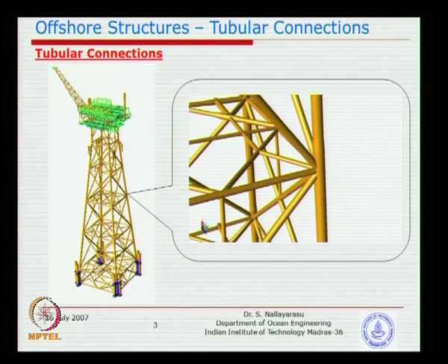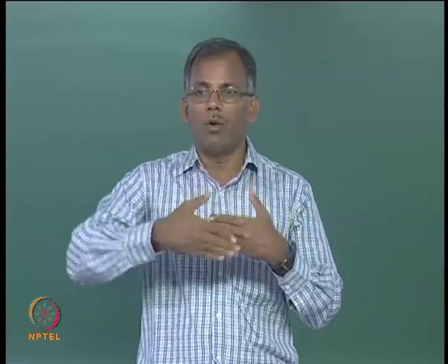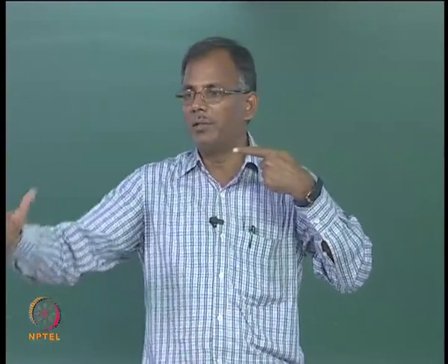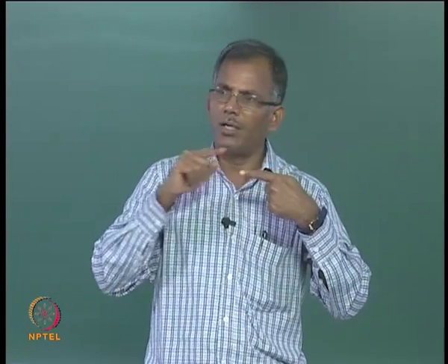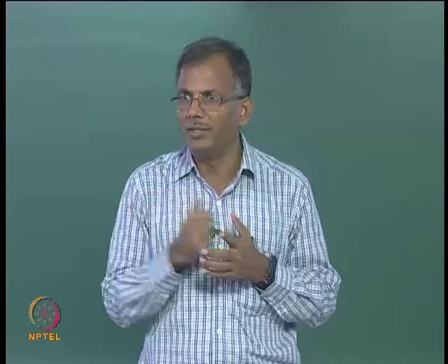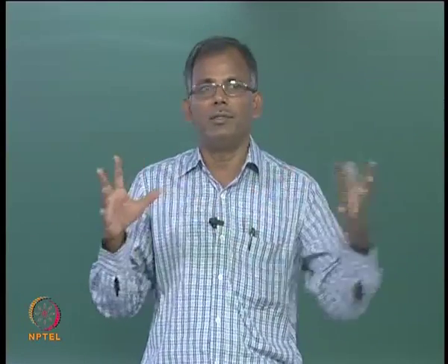So the design procedure adopted in the last 20-30 years is to design plane by plane, but then for the interaction between plane 1, plane 2 and plane 3 you actually have multiplication factors. For example, I have one brace in this plane, another brace in the perpendicular plane and another one in the diagonal plane. Basically all three are going to deliver the forces simultaneously, but I do not have a design tool to do the design for three together.